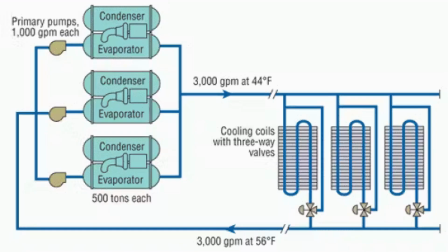Design by system size. Small systems, 1 to 2 chillers. Focus on simplicity. Air-cooled chillers with single-loop or variable primary designs minimize complexity. Wider delta T values can reduce pipe and pump size, cutting first cost. Often, these systems run unattended and use automatic enable-disable based on ambient temperature.